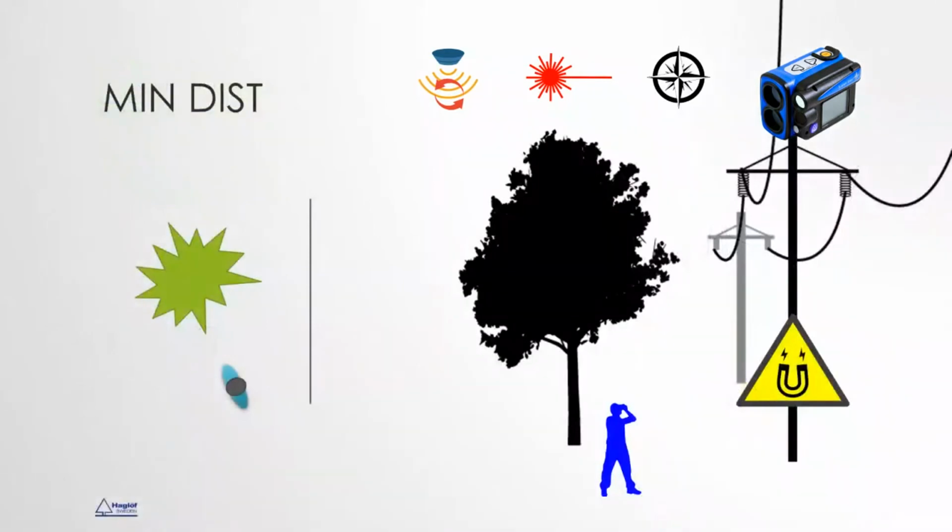You step out from the power line, because you should avoid being in the line, because the compass, as you know, will have a problem inside the line because of the high voltage, the electricity there. It's the same as you should not use your cell phone nearby. You should not use metallic objects, it could be your car keys or anything like that, because it could interfere with the compass. So here we step out from the line, and now we want to measure the nearest distance from the branch to the line.